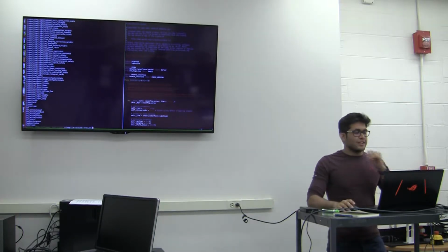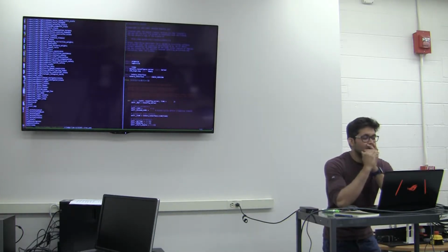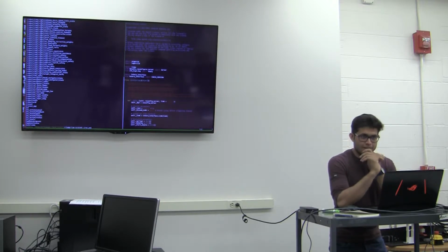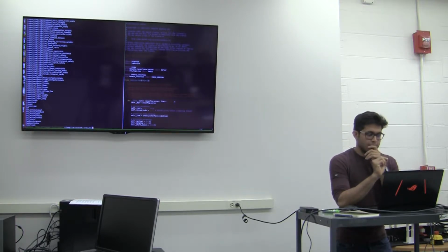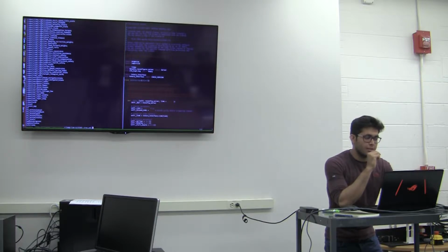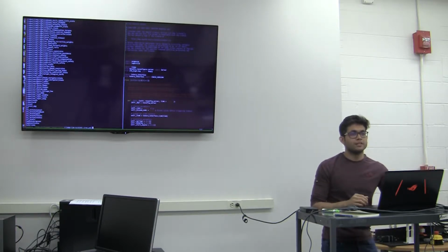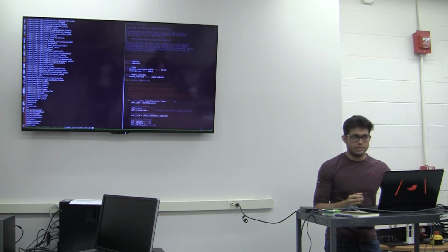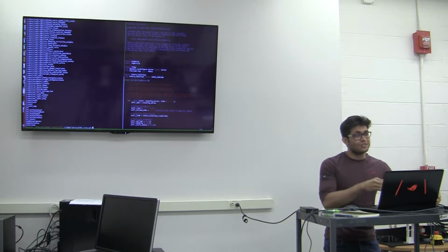Yeah, too big, right? This is every topic that the robot is publishing right now, and your laptop is communicating with it. So you see all the topics: limb, right command, end state, endpoint state, joint command, joint state, limb state. These are all the parameters that you can work with. Some data is read-only, and some topics you can publish on. So these are all the topics that you need to worry about. That's why it's rostopic list.